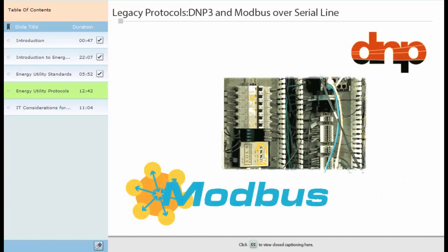Transitioning from legacy protocols and older standards has become increasingly more common. The new trend in adaptable communication protocols is the IEC 61850 standard, which supports interoperability within a multi-vendor environment. The structure of the IEC 61850 is highly advanced and object-oriented. Modbus, a well-known legacy protocol, was designed for very low bandwidth rates that can run on EIA 232, 422, and 485. Modbus works as a master-slave protocol, where the master initiates all communication. The protocol allows up to 247 slaves per master.